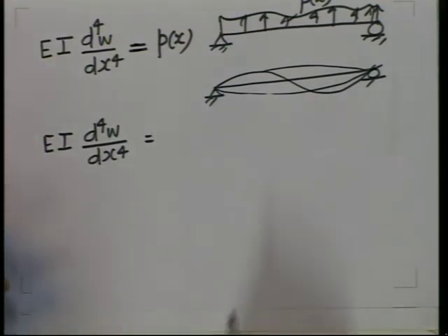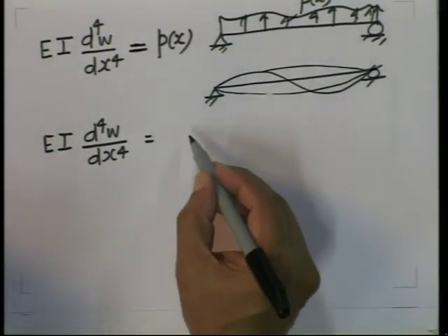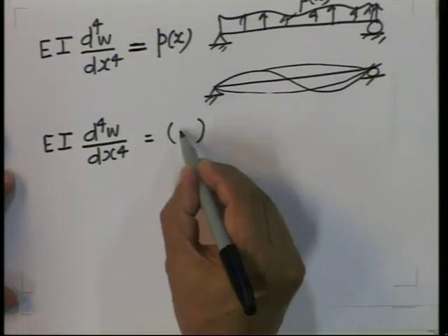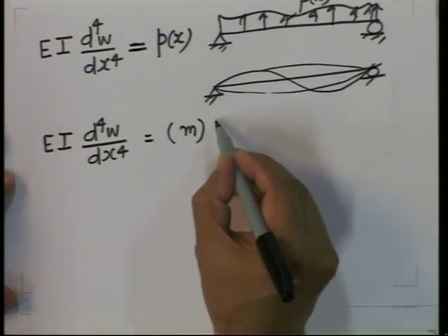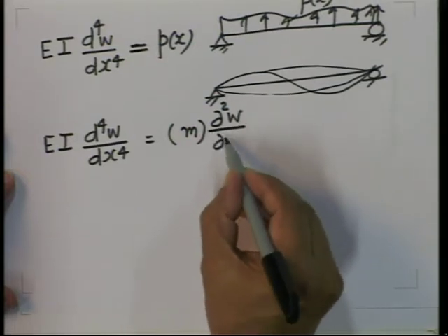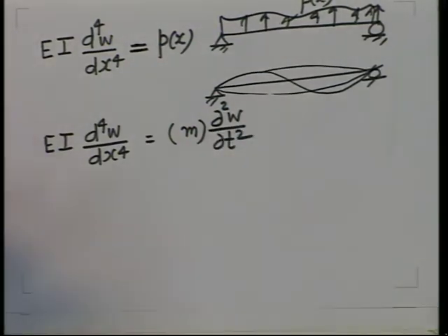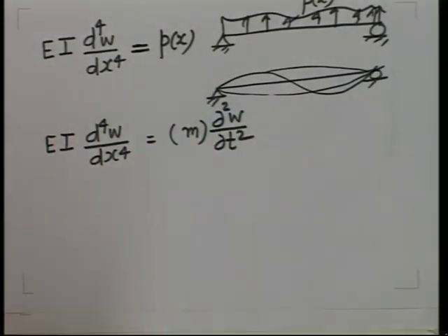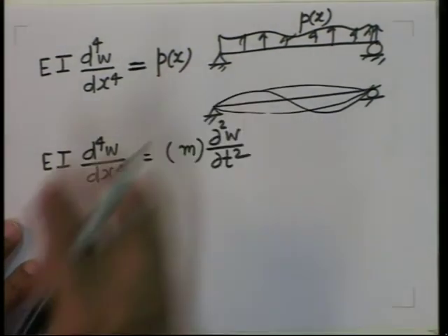It is not rho A, because it will involve curvatures; moment of inertia comes in, but anyway some mass parameter will come, multiplied by d square w by d t square. So, that will be the time dependent problem, and this will be the static one. First we will study how to take care of this.